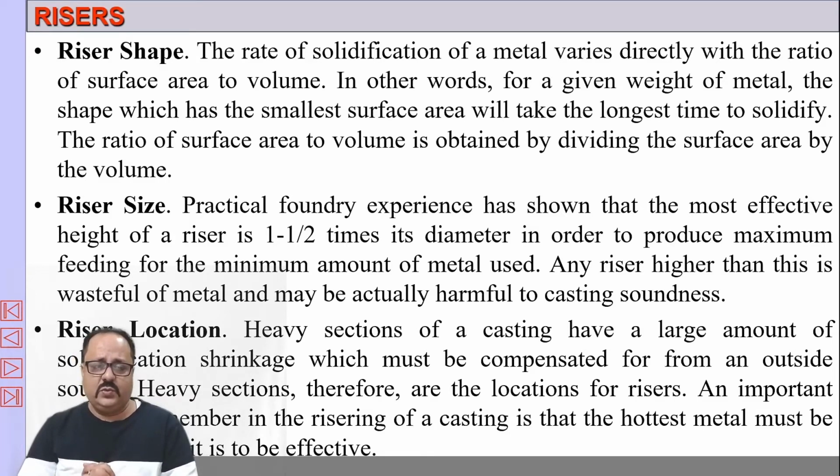And where should you locate the riser? Obviously you will locate the riser near the heavy sections, where there will be much more shrinkage. To compensate for the shrinkage, the riser will be placed near the heavier section of the casting. So these three are important. Basically, what we learn now is that riser location depends on your casting shape, which section is heavier.